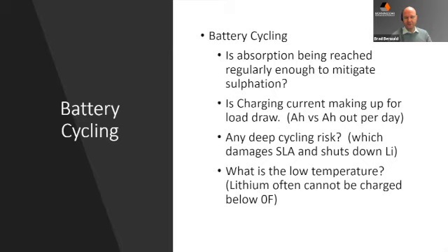When you get into looking at the battery capacity and the battery's overall health, obviously, looking at the voltage and making sure that your loads are up is useful, but you also want to make sure absorption is being reached, because you may have PV going in every day, but if you're not getting into an absorption stage, especially critical for lead acid batteries, to mitigate sulfation, then you're already operating on borrowed time, because if that sulfation occurs, the system could go down at some point in the future and you're losing capacity.